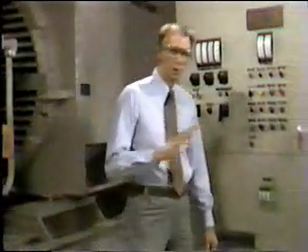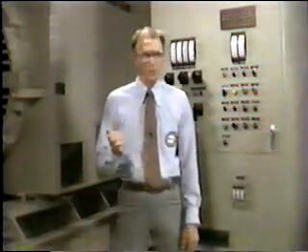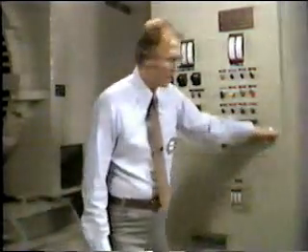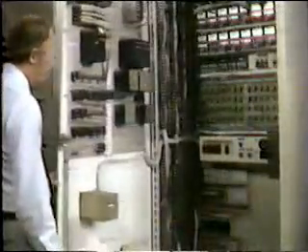During engine operation, the governor will maintain a controlled engine speed. The governor will also maintain equal load sharing between two or more generators operating in parallel, and it will ramp the engine speed between 90 and 100%. Now let's take a closer look at the governor, which is located here inside the control console.